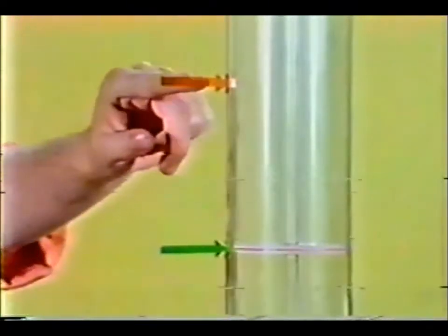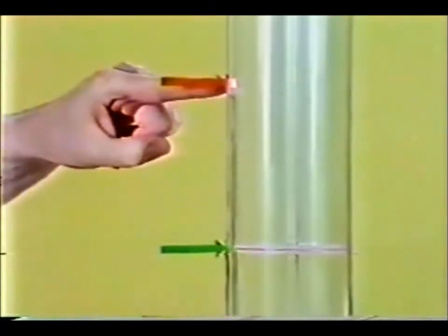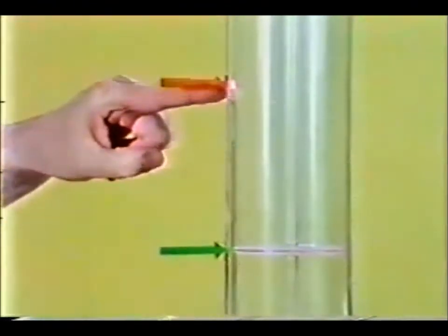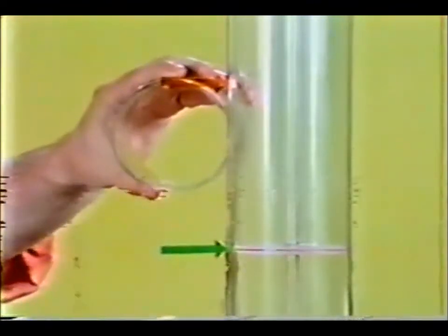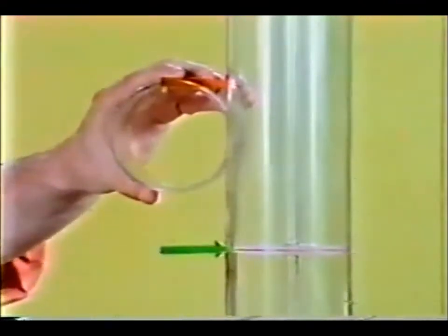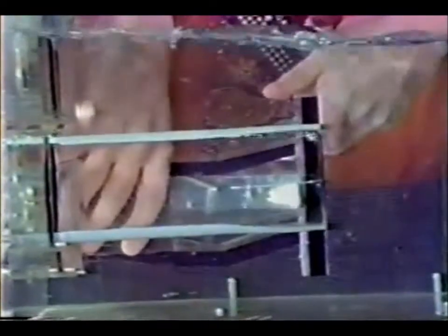Comparing this headwater elevation with that for the thin edge projecting inlet, you can see that the headwater has dropped from here to here. This drop amounts to 1 1/2 pipe diameters. By using the side tapered inlet, the contraction at the entrance of the culvert has been minimized. Another method of increasing performance is to lower the control section of the culvert. This means placing the throat section below the stream bed. This is accomplished by using a slope-tapered inlet.